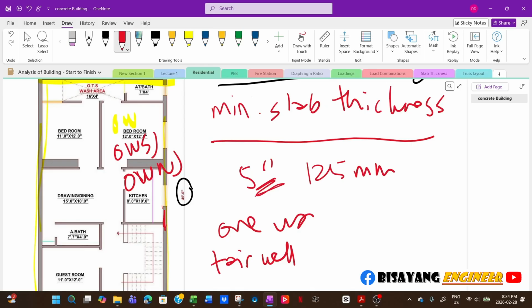The architects would not like a column that is too big that will encroach, for example, in this location here. That's why you could have your column on this side so that the clearance, the minimum opening width in that area, will not be affected. Otherwise you will have to shorten the wall, which will reduce this area. So the best location, if you want to have a column in this area, would be right here.